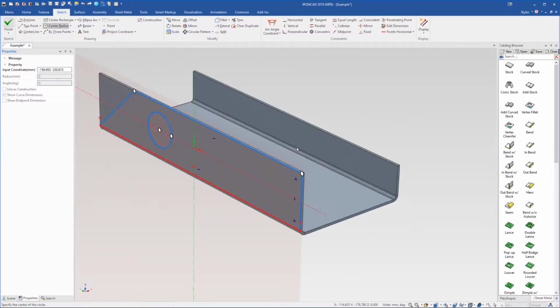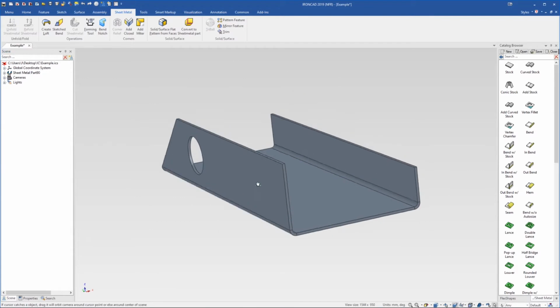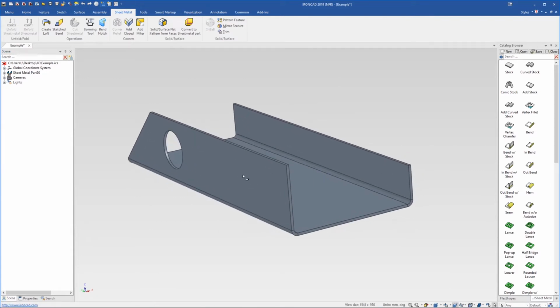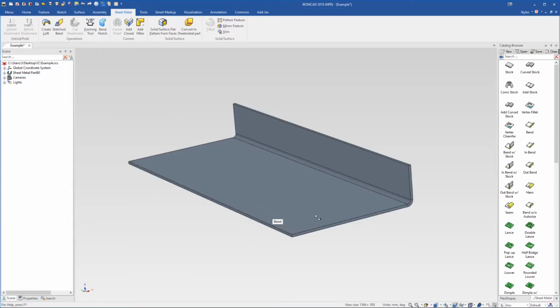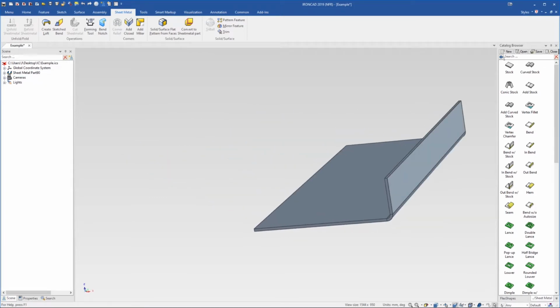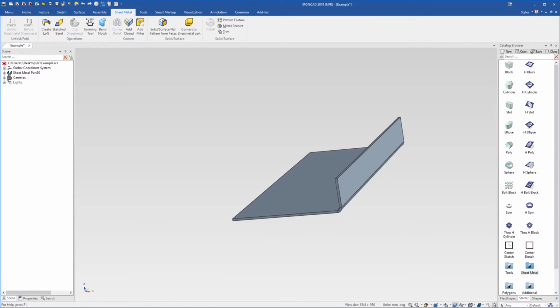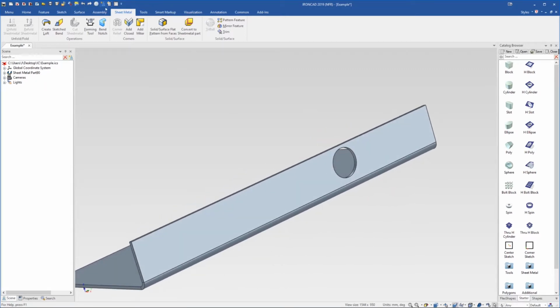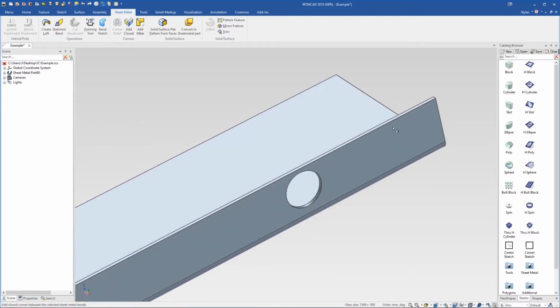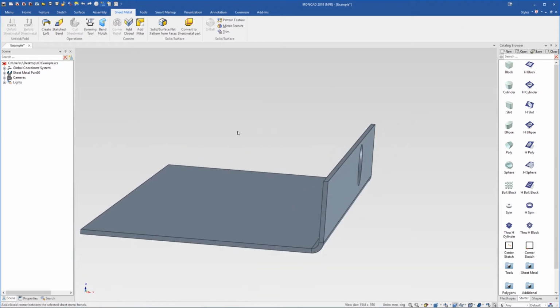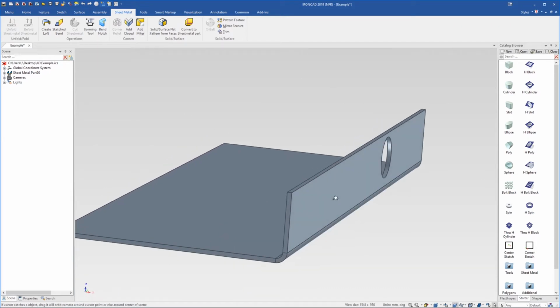Quick example, we'll edit this sketch really quickly, and you can see it's very easy to customize that. Whereas if you were doing the same sort of customization with a bend, you would generally want to do it with a cut. So we'd go into our IntelliShapes, and we drag and drop out an H block or an H cylinder, for example, to cut away that geometry. Both are useful in different cases, but for using the Mitre tool, as mentioned earlier, you only want to use bends.